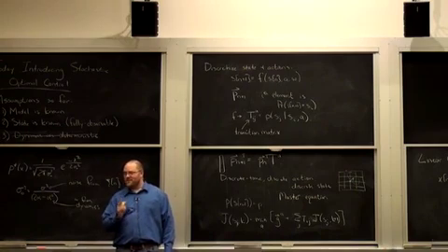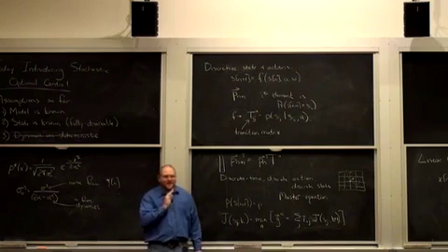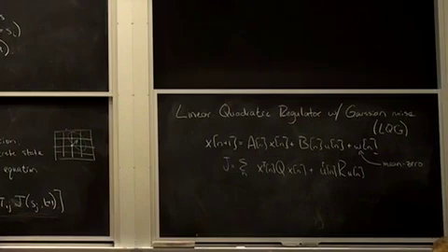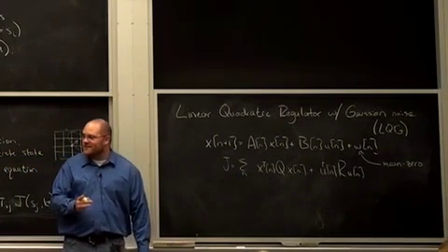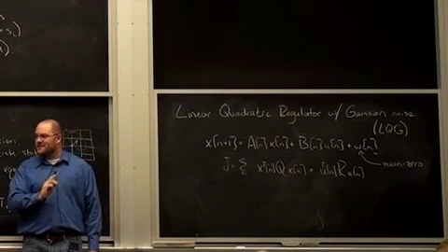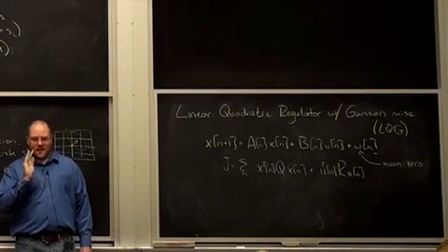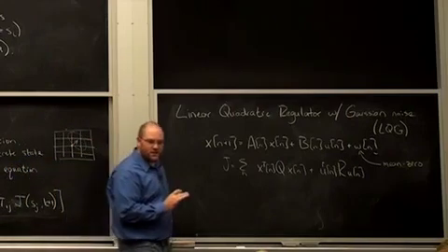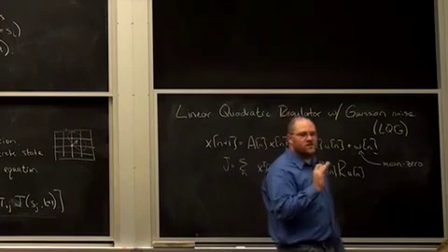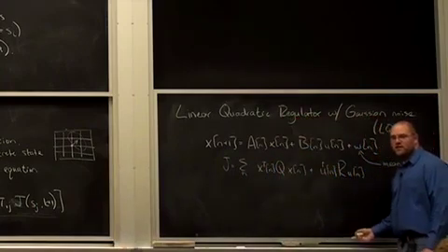Yeah, it turns out you wouldn't act differently. It's one of the most surprising results, I think, of stochastic optimal control. It turns out that you work it all out, you put your costs like this, and you don't turn your gains up because of the disturbances or anything like that. The optimal solution for the stochastic case is the same policy as the optimal solution for the deterministic case.